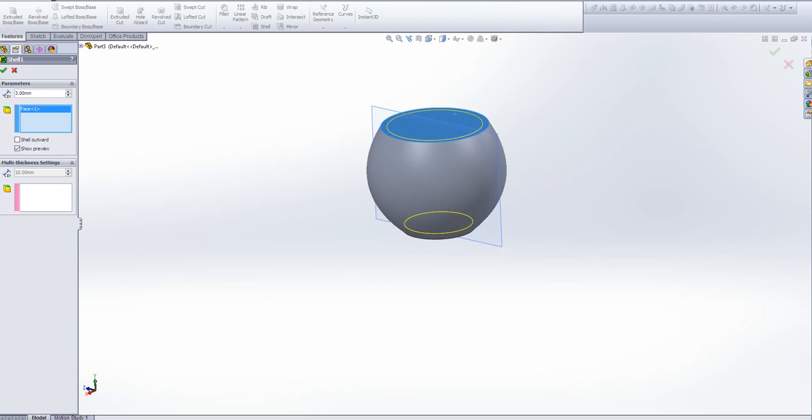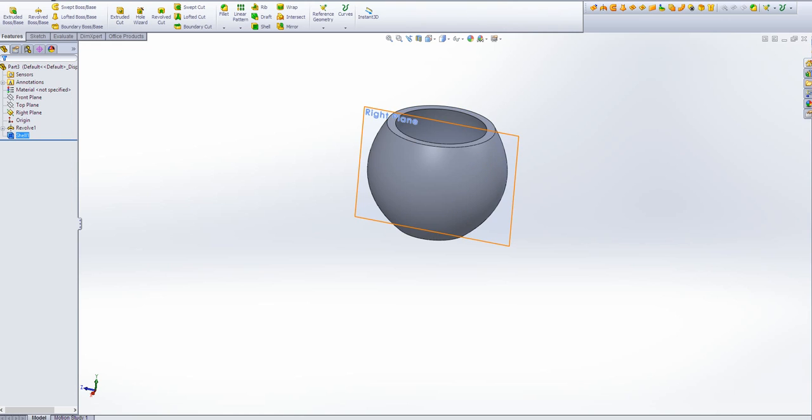So essentially what it's doing, it's cutting down from that face, and then every other thickness, I should say, will be about 3 mil thick. We can increase that to 4 mil, and however you like. It depends what you really want.